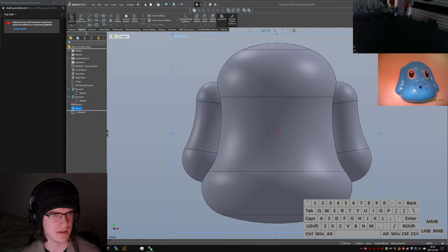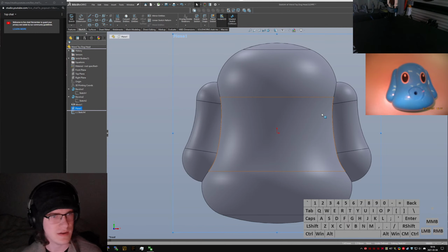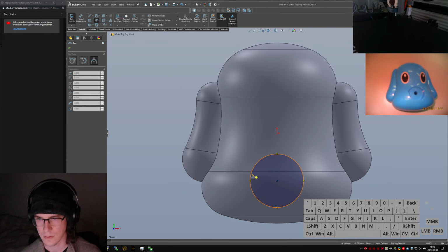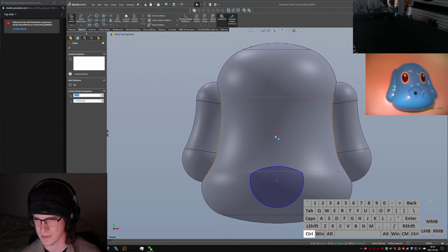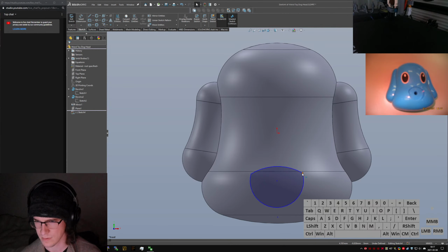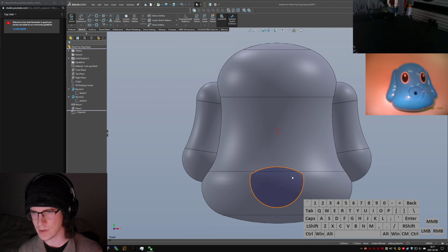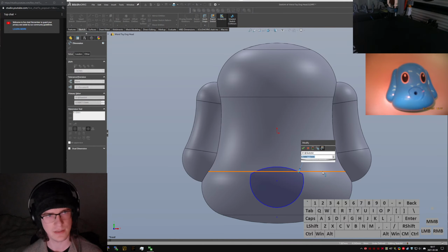And we have kind of a... I can blow this up a little bit. We've got kind of a circle with a cut top on it, so quickly replicate that. Kinda that-ish. Select the center point, make that vertical. I'm just gonna select these 2 points and make them horizontal so it lines up nicely. There's no real right or wrong way to do that as long as you can come back and see, and it's obvious how things are aligned.